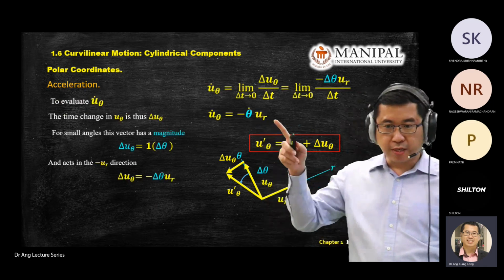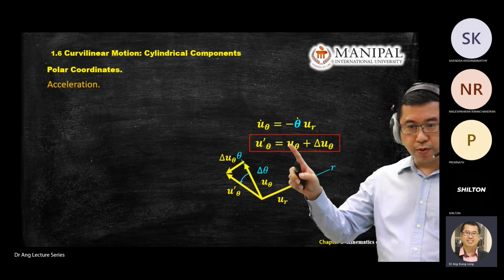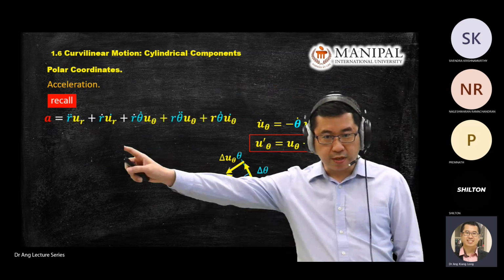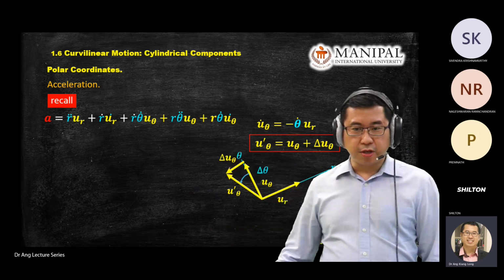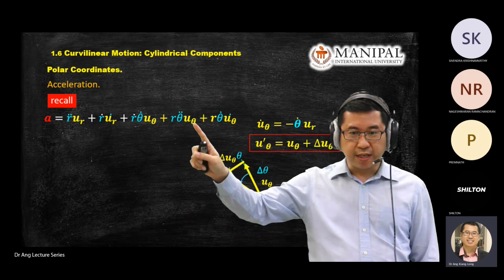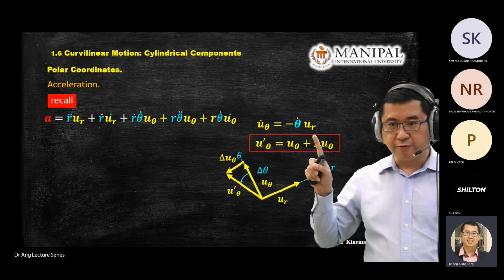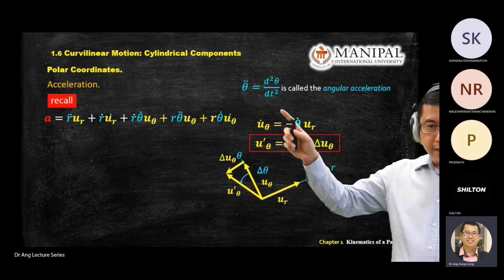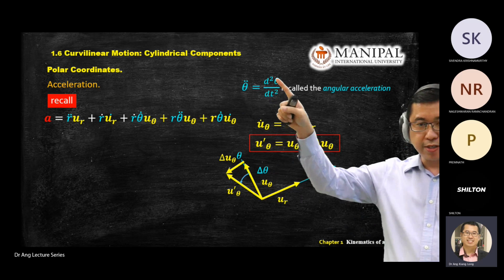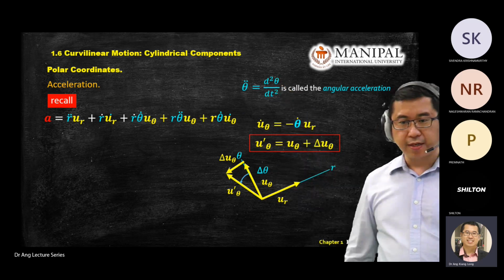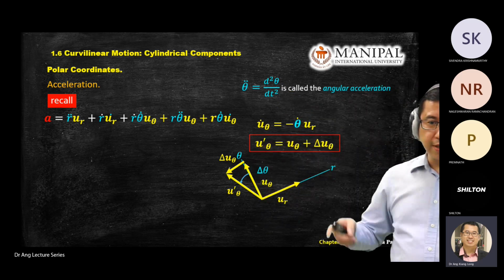Okay, I pull this equation to here and I erase all the equations on the board. You have two equations here. Recall this very lengthy equation. Substitute this one inside there because you want to remove all the U theta into R form. This is just add-on information. What do I mean by R double dot? It means the double differentiation, second order derivative, of your angle. You differentiate and then you differentiate one more time. This is the angular acceleration, just add-on information.